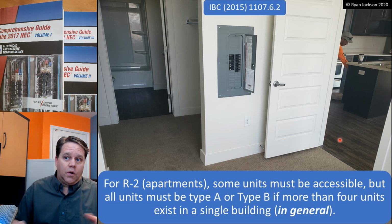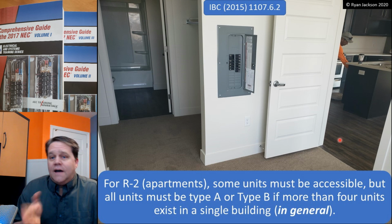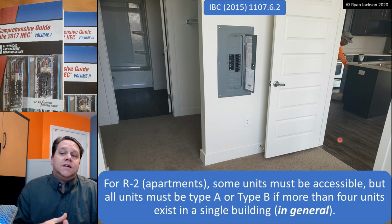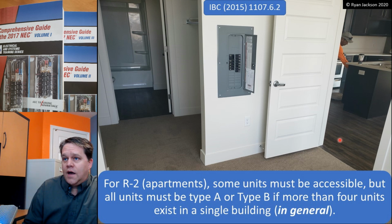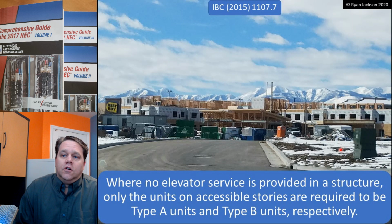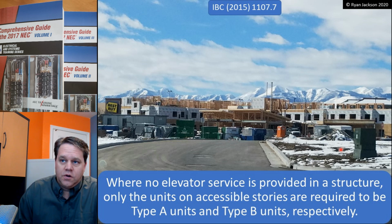So if we look at this again, some units in apartments have to be accessible, but all units have to be at least Type A or Type B, adaptable, if you have more than 4 units in a single building. Now that's generally speaking. There are some exceptions to that, so be aware. For example, if no elevator service is provided in a structure, only the units on accessible stories are required to be Type A or Type B units respectively.